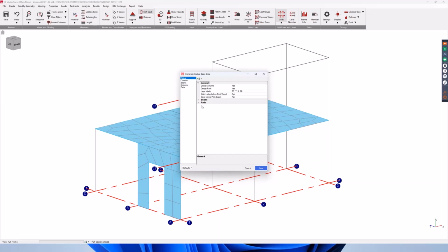Okay, just quickly review the settings. So let's start with the common. For example, under the concrete, we can specify the aggregate size and ask the program to auto-calculate the code theta for maximum shear capacity. Under reinforcement, you can set your reinforcement steel grade, which is 500B for both the main bars and then the links by default.